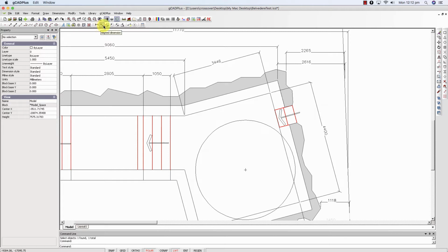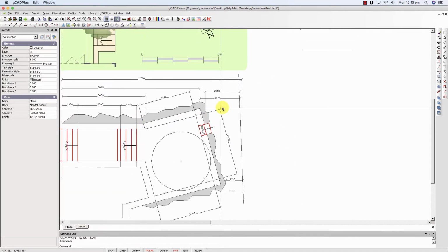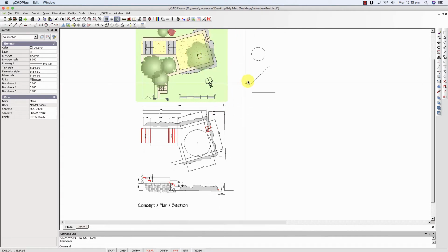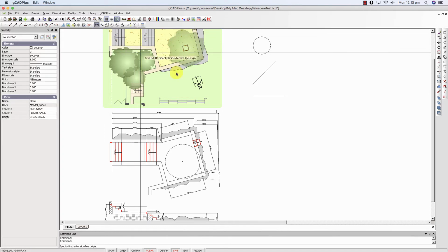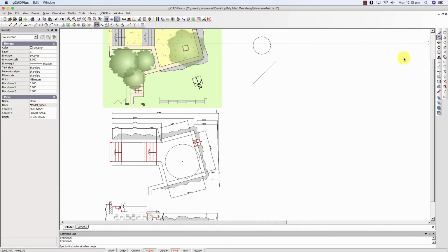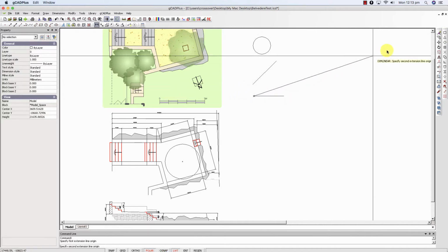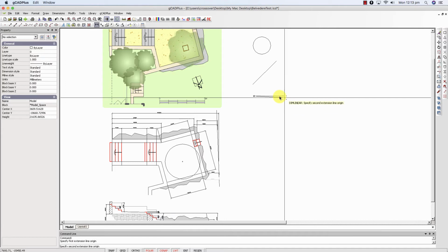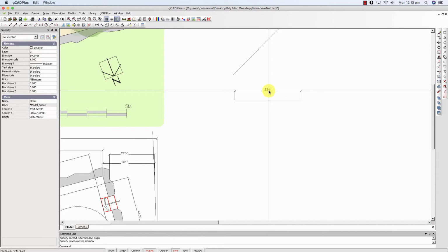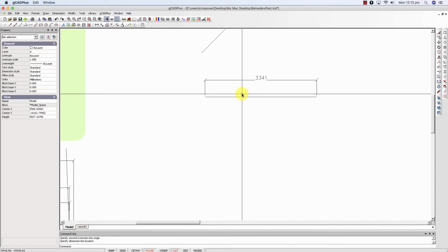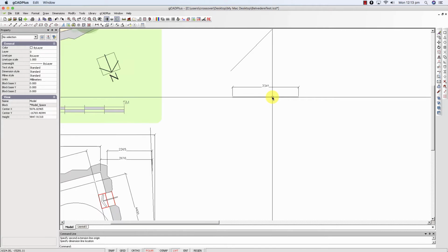Linear dimension, the line dimensions and so on are all here, circle diameter and so on. And they're very simple to use. If we just come over here now and zoom in, if I want to apply a dimension to that line, I just take the dimension tool, and it's a good idea in this case when you're doing some dimensions to leave the O snaps on. I have to pick them here, and I can move the dimension up, and the dimension takes its value from the object itself. So it's a really good check of your underlying design work.